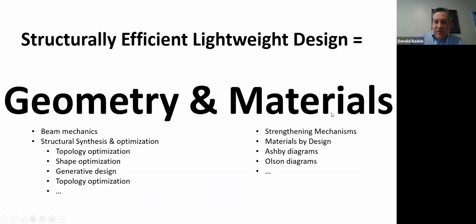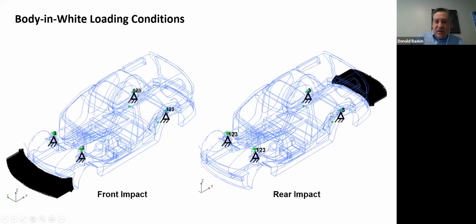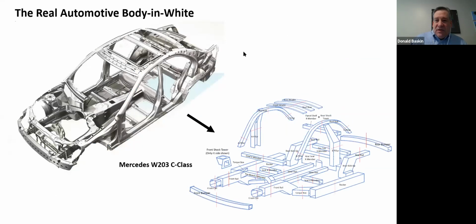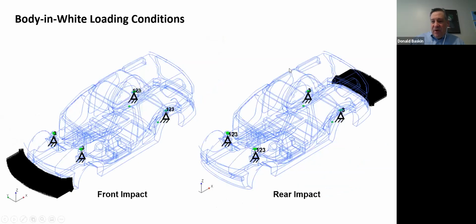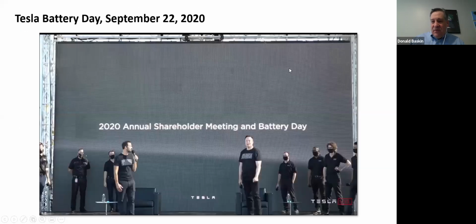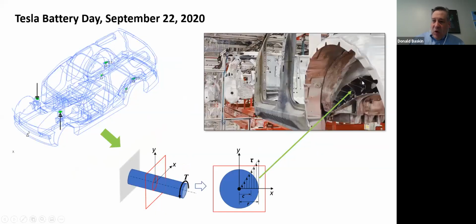You know, if you go back and look at this Mercedes here, and this is a steel structure. Can you see it? No, I guess you can't quite see it. Anyway, the same panel on this car, the same rear rail structure, is made with just a box section, and that very outside panel portion of the part is a solid piece that would be much more efficient at taking that global torsion load. So maybe there's a better way to do this.